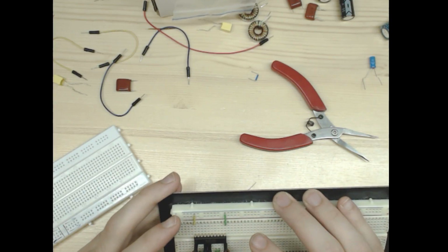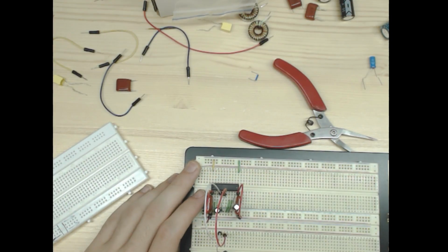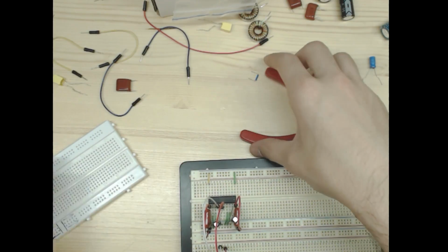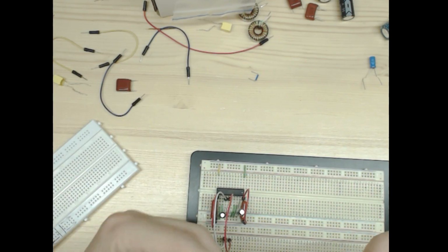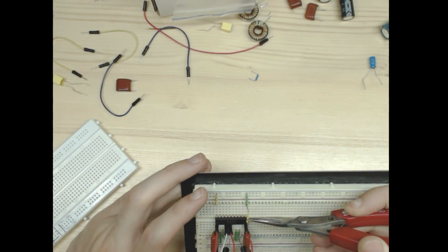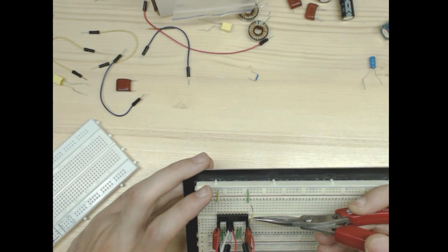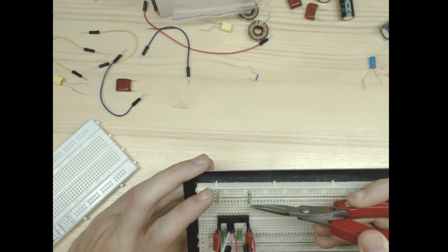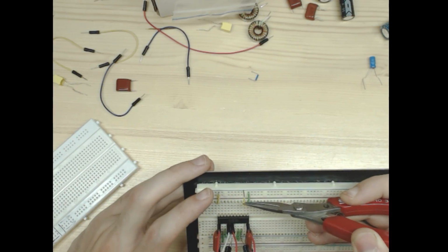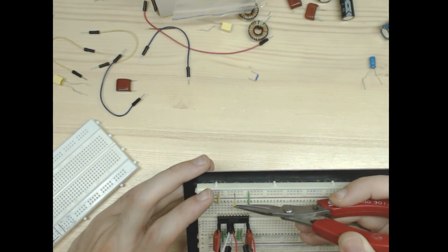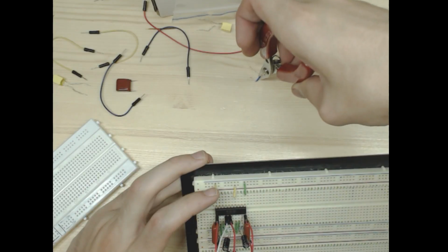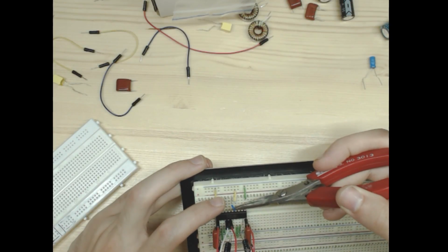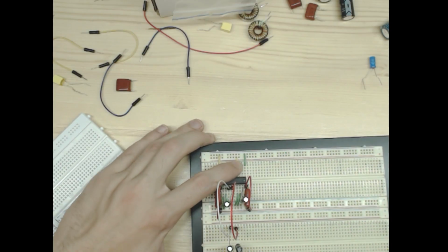Okay, so next on the list we have to deal with gain pins. Gain pins are easy enough. All we have to do is look for pins number 14 and 15. So this is ground. This is right out. This is bootstrap. Gain 1 and 2. So we're going to set this high, as well as this high. Like this.